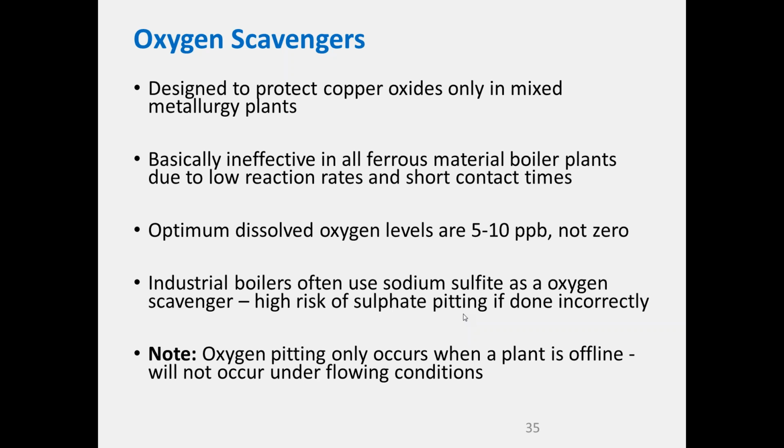So, you know, if you've got pits in your plant, and we'll talk about this in the next webinar, but if you're seeing pits that are growing, what it's telling me straight away is that you've got a layup and storage issue. Your plant is wet when it's shut down, and you've gone oxygen saturated, and you've got no flow, because oxygen pitting doesn't happen when the plant is in service. When you've got flow over the surfaces, you disrupt that galvanic process, and it doesn't occur. But yeah, that one's commonly misunderstood in the industry.